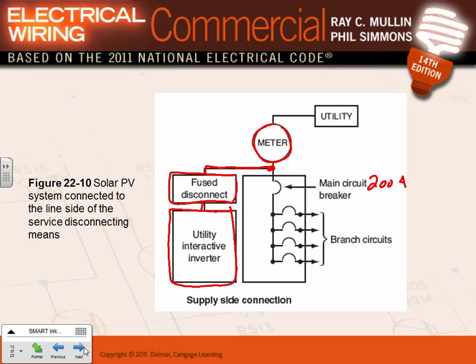No limitation in how much current you can pull here. You can put as much current as Xcel allows you to. So if you have a 200 amp service, I can push back 400 amp into Xcel, granted the wires are rated for it, because you have to push back through the wires. If you have 200 amp wire, you can't push 400 amp into it. So there is no limitation by code on how much power you can put through this system. The only limitation is how much current the utility is going to limit you to, of course. No limitation if you do it this way.